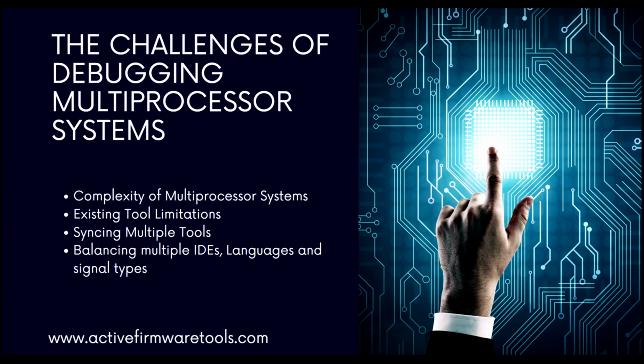One of the biggest problems is that the existing tools that are out there on the market really expect you just to look at one processor at a time. You can get things like logic analyzers, which will show you the signals of your entire design, but it doesn't dive into the debugging of your firmware at all, unless you do a little bit of bit banging and that kind of thing. But the problem comes when we're trying to find some tools, and today we're going to show you some clever ways to get around that limitation.